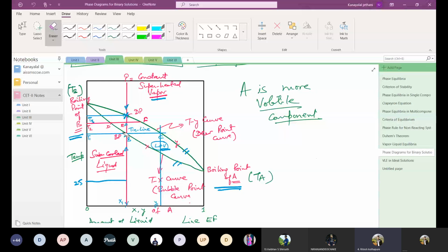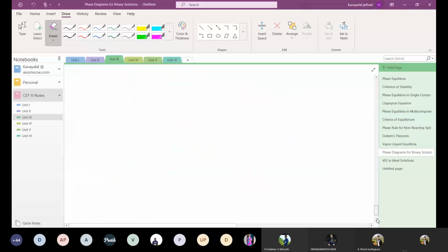And sir, if we take a component at the same temperature, y1 will be greater than x1, right? Yes, y1 will be greater than x1 for the more volatile component. That's why we are plotting only the more volatile component. We are not plotting the less volatile component. The more volatile component's composition will be higher in the vapor. For the less volatile it is the opposite, meaning lower. Because the less volatile is always at the bottom, which we saw in the distillation column, right?